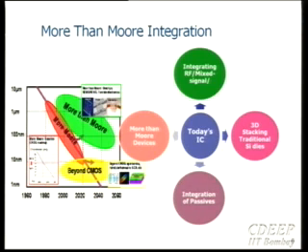Integration of passives into your devices is also important, and in the mixed signal domain that turns out to be quite important, with inductors and so on integrated into today's ICs. And of course, the trend has been integrating RF, mixed signals, and so on. But that's not the domain that I'm going to be talking about. That's hybrid certainly, but that's not the domain I'm going to be talking about. I'm going to be focusing on some of the more than Moore devices, the devices that can give you auxiliary or ancillary functions to silicon CMOS and give you low cost, lower power consumption, and better robustness.